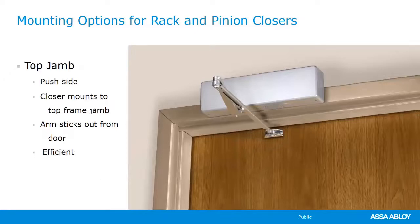it kind of looks like the inverse of regular arm, but now we're on the push side of the door. The door closer is mounted on the Top Jam, that's why we call it that, and the arm is mounted to the door. Again, we're 90 degrees off of that door, making sure that the arm is in the right position. So if you see a Top Jam door closer and that arm is not 90 degrees off of the door, something's wrong. Something's not mounted right, it's not adjusted right, it's not indexed correctly. So check that. These are also very strong and very efficient. Again, not as aesthetically pleasing.